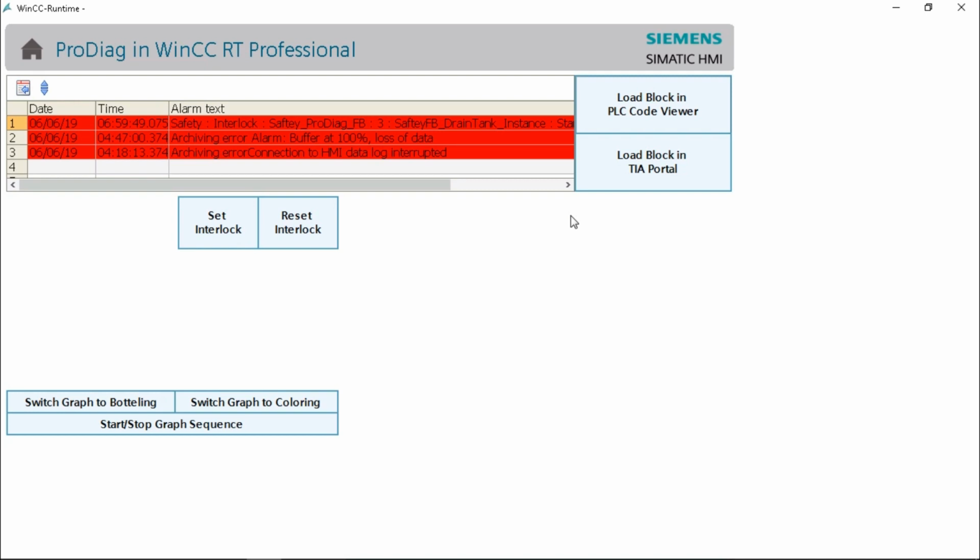But what I want you to do first, to get a little bit more familiar with the configuration of such a tag supervision, is the hands-on I included in the slides, which is this here. So we create a supervision from the safety DB as an interlock, and I also put in which condition here to find the FB3 in the demo project itself.